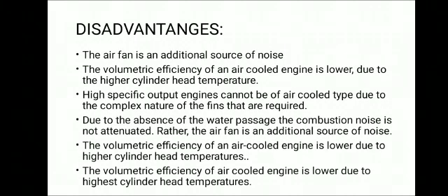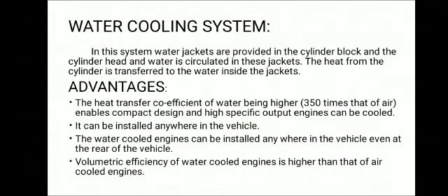Disadvantages: the air fan is an additional source of noise. Volumetric efficiency is lower. High specific output engines cannot be used. The volumetric efficiency is lower due to higher cylinder head temperature. Water cooling system: in this system, water jackets are provided in the cylinder block and cylinder head, and water is circulated in these jackets.